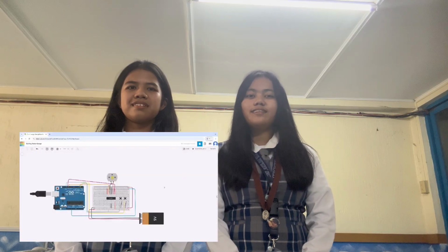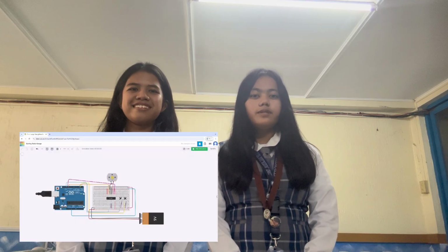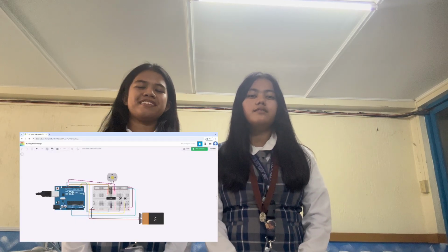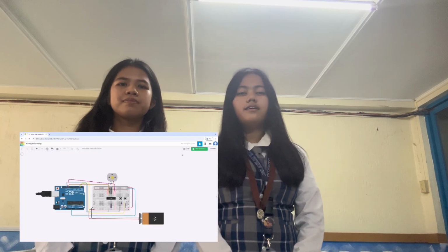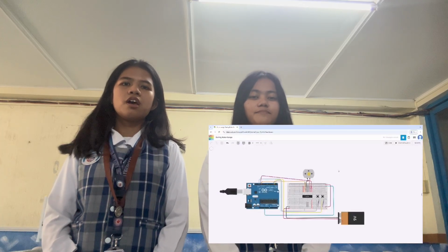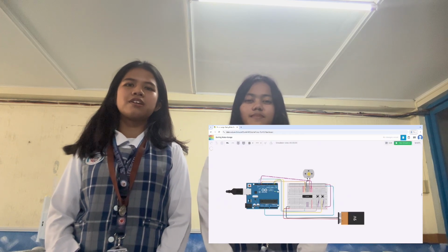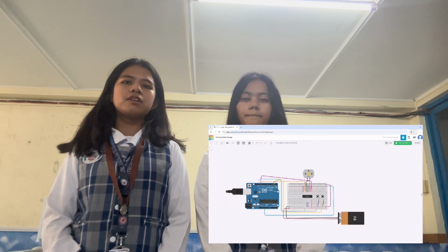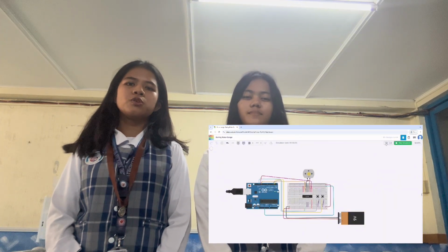In the second activity, we use PWM with the same setup to control motor speed. The Arduino gradually increases and decreases the speed, showing how digital signals can mimic analog control. In the third activity, we use the same setup to reverse the DC motor's rotation by adjusting signals sent to the L293D. 2 Arduino pins control the direction by changing the motor's polarity through the H-bridge.